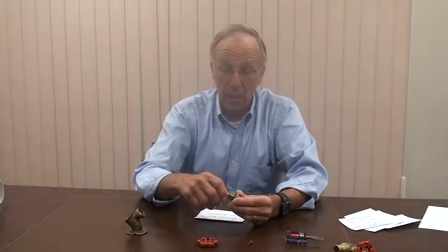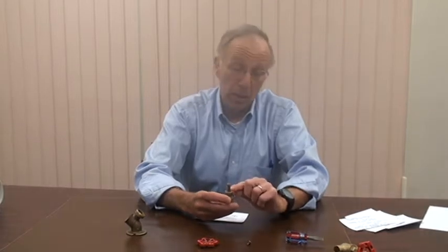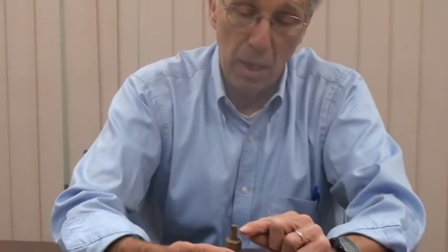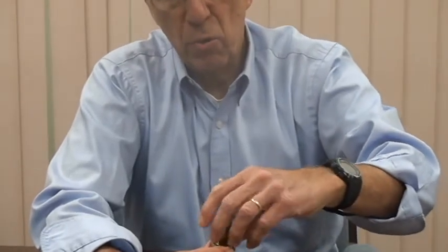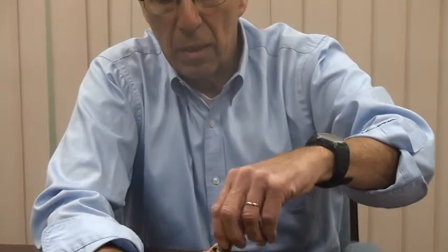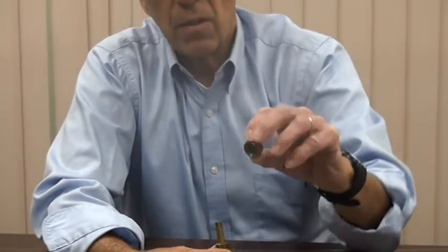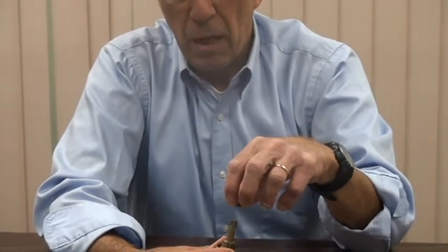Now, one of the important things is the faucet can't leak, so there has to be a means of keeping the water from coming up the stem and coming out in this region. So here we have a threaded nut. Now, there's actually two pieces I'm taking off, only one of which I will be able to display, but the purpose of this piece is to seal the stem to the body of the faucet and prevent leaking.